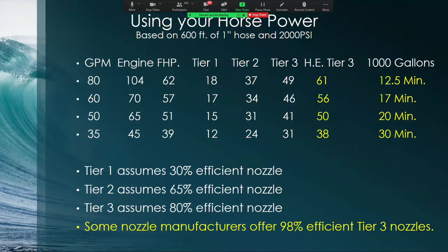the Vactor pump is a piston that moves back and forth, and every time that pump cycles, and what I call a cycle for a Vactor truck is full left hand and then back full right hand. In other words, a stroke out and a stroke back. That moves 5.5 gallons of water every time it goes through a cycle. So if I'm putting 80 gallons a minute out, that thing must run over 15 cycles in a minute to give me 80 gallons. At 50 gallons, it runs 9. And at 35, it runs just under 7. So at the end of 2 years, 3 years, 4 years, the wear and tear on that pump is dramatic. Or the lessening of wear and tear on that pump is quite dramatic.